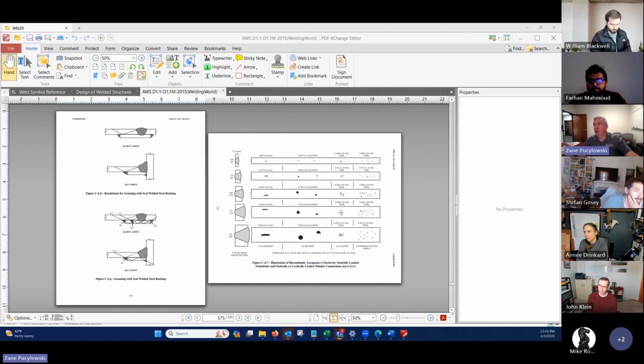References for stacked reinforcing welds. That's a really good one, Trey. Normally what I do there is just look at them independently as to what share of the load they can each take. And I think if you're conservative enough in your weld calcs anyway, that should get you in the neighborhood.